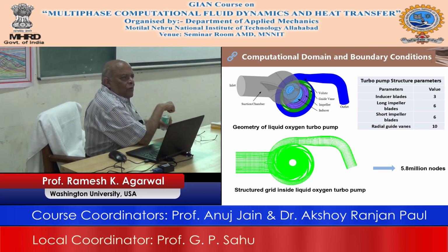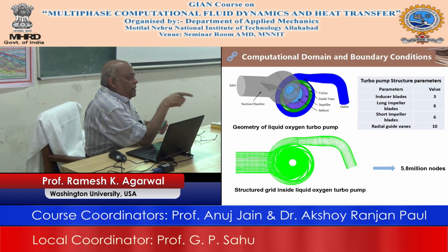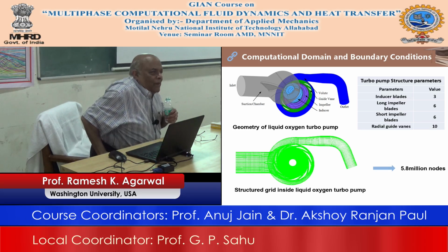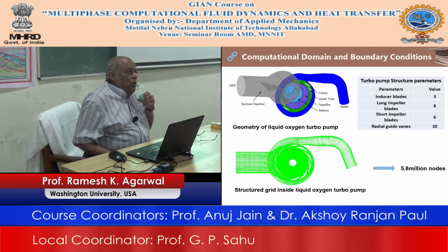So you treat it as a single fluid, and you have a continuity equation, momentum equation, in which the density is calculated as a fraction of liquid plus fraction of vapor, and then viscosity is calculated as a fraction of vapor plus fraction of liquid, etc. But the volume of fluid equation now has a source term. Now this capability is not included at the time we use it. So which means that we have to modify the volume of fluid equation by putting in a UDF. But I don't know, the latest version might have this capability.